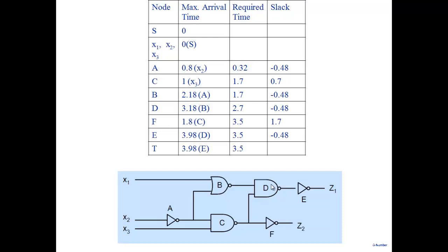Now, it meets the timing, but if the slack is 0.48, you may have used a much larger NAND gate in your initial design in order to lessen the delay. Generally, as you increase the size of a gate, its delay goes down. So if you see a positive slack of 0.48, you may decrease the size of the NAND gate, because there is a very large margin. So you can intervene in your design, modify the sizes of the transistors, and take advantage of this information.